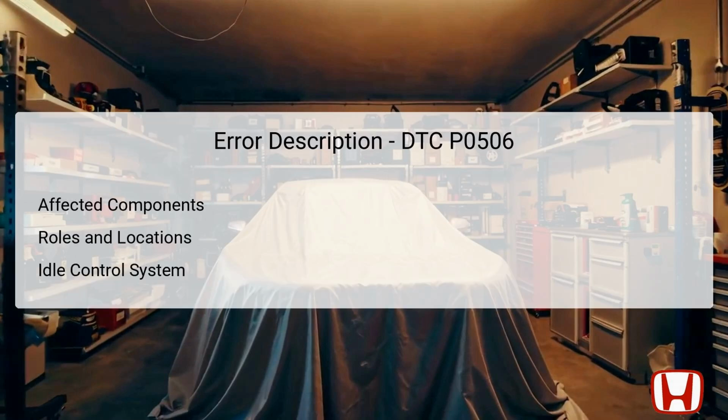DTC P0506 pertains to a malfunction in the idle control system, which consists of several critical components. The primary components include the accelerator pedal position, APP, sensor A and B, throttle position, TP, sensor A and B, and the throttle body. These components collectively work to measure the position of the accelerator pedal and throttle to adjust the airflow entering the engine, thereby controlling idle speed.